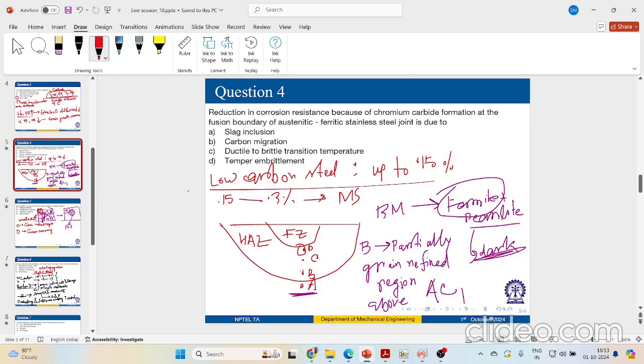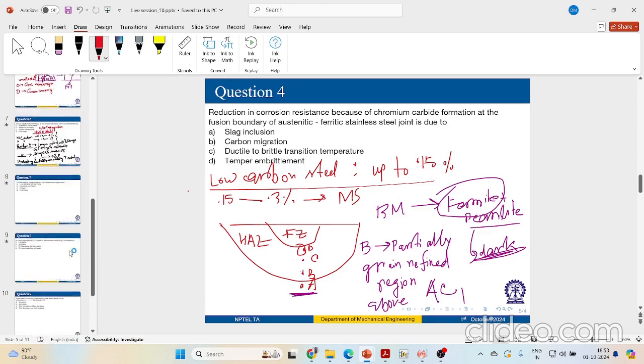That we know, right? That is well known from the physical metallurgy of steels. This transformation increases the hardness and brittleness, and that generates some tensile residual stress in your structure, right? So that makes your steel prone to cracking. So there is something called cold cracking or hydrogen cracking.